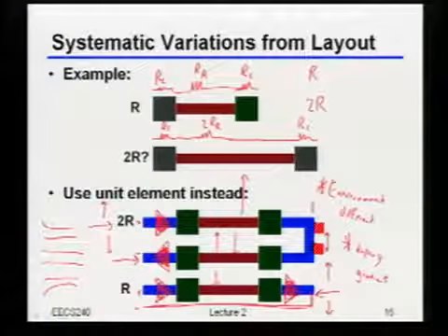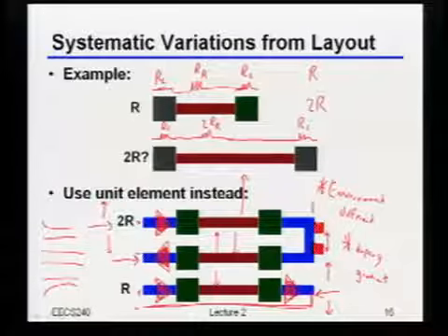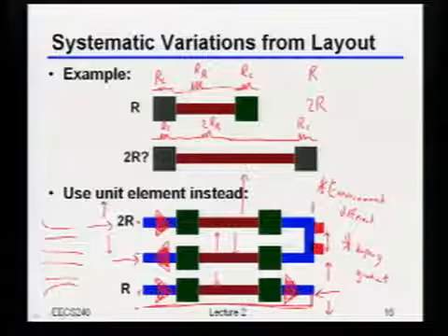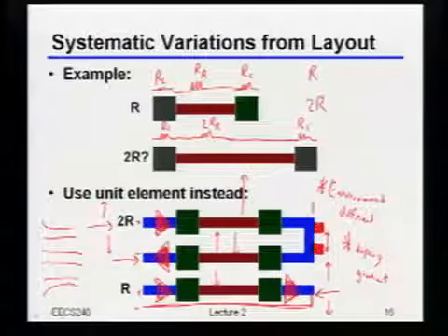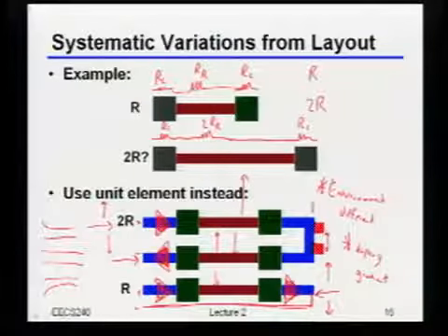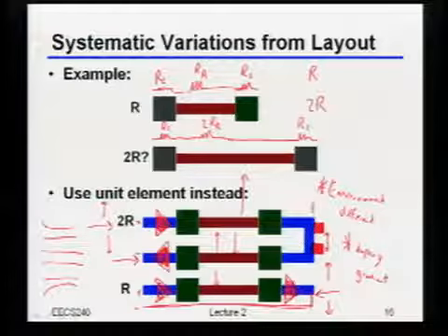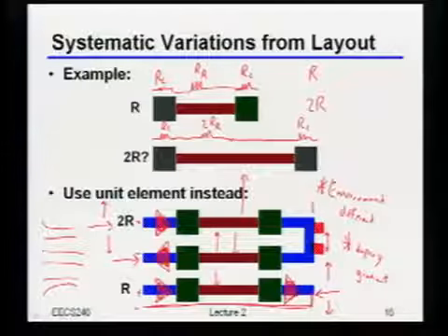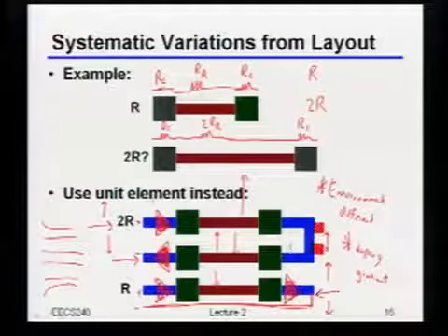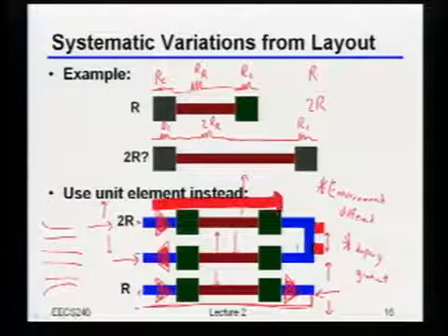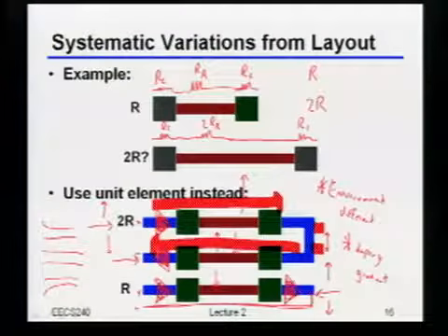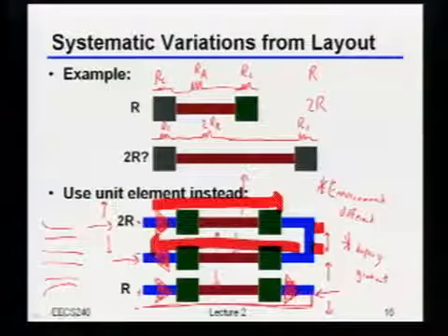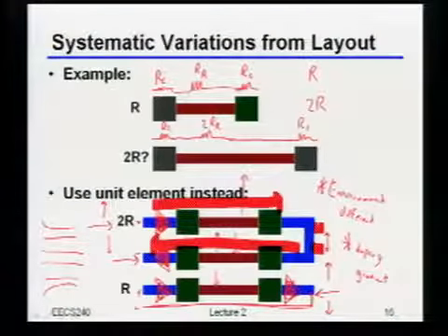That doesn't make a difference? Turn what around? The poly resistor. No, because even if, are you talking like 90 degrees? Yeah, even if you turned it 90 degrees, actually that's in some sense 180, even worse, right? It's symmetric, but notice I've got current flowing in two directions here. In this one I've got it flowing that way, and in this one I've got it flowing that way. Okay, so it is symmetric. So that'll happen just because of direction. Yeah, it's just direction. So the symmetry is not the problem. It's purely that the direction is different.